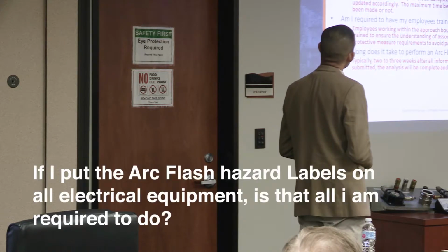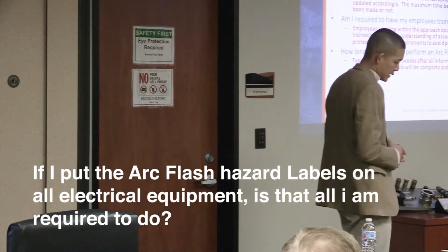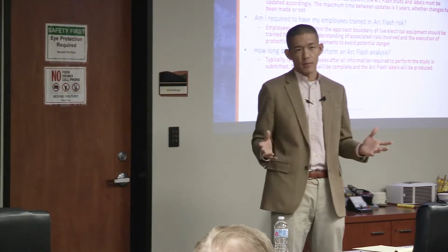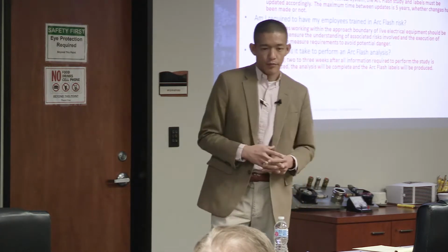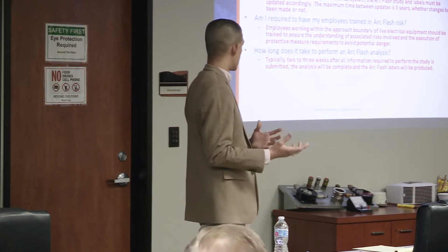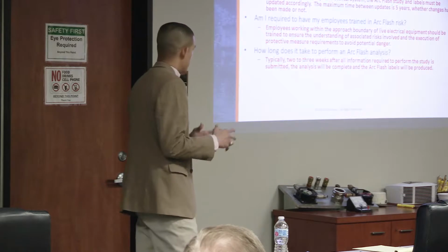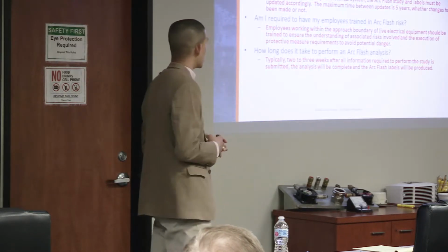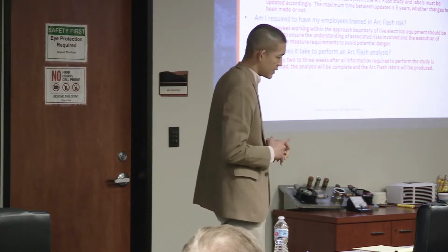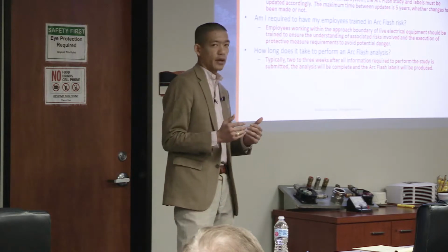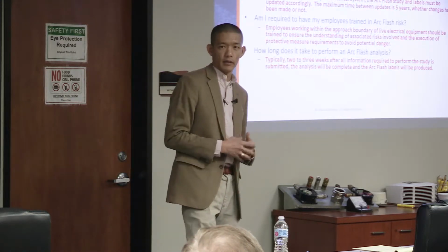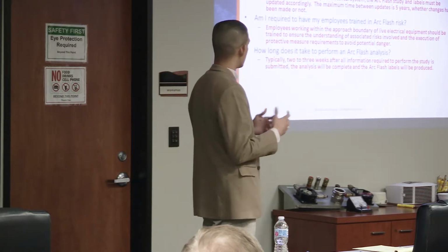Yes. So putting labels on, some people think that after we give them the stickers, once they put the labels on, their job is done. Whether it's the vessel owner or the building management team, their job is not done. They have to update those studies every 5 years, and it's still there. They still have to do their job and make sure that anybody working on their equipment is actually trained to wear that PPE and work on that equipment, regardless of whether the stickers are out there.